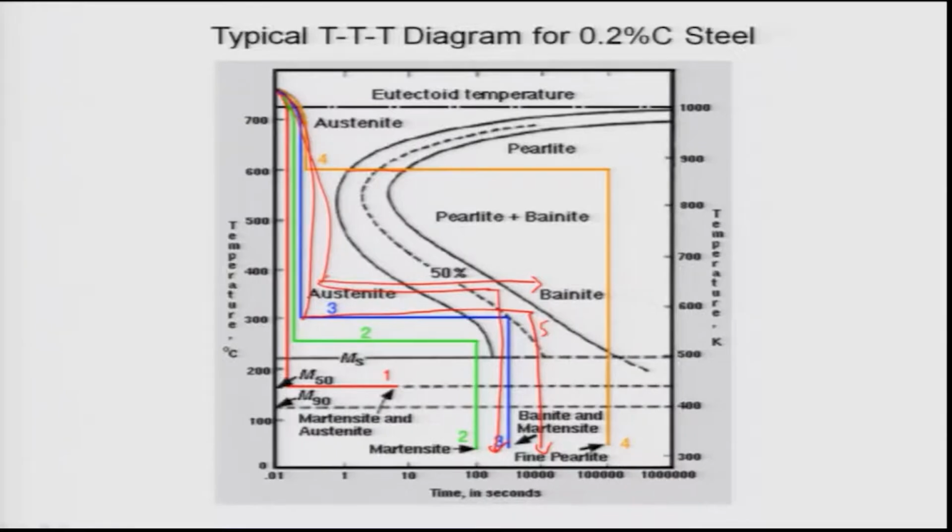And once the pearlite forms, the sample can be easily cooled, because once complete transformation of austenite to pearlite happens, nothing else can happen, whether you quench it or cool it slowly, does not matter. But normally it is cooled rapidly so that the pearlite which is formed at high temperature does not get changed when it is investigated further.